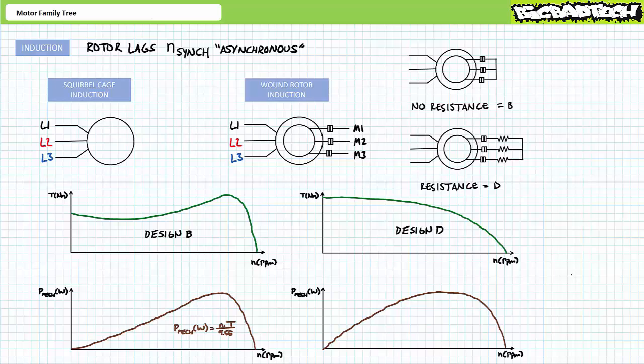You used to see this method back in the day before motor drives, but only on rare occasions would you see this today. Now, motor drives make the direct control of excitation frequency a more efficient means of speed control than does varying rotor resistance of wound rotor induction motors. We'll examine motor drives and wound rotor induction motors in greater detail in later lectures.